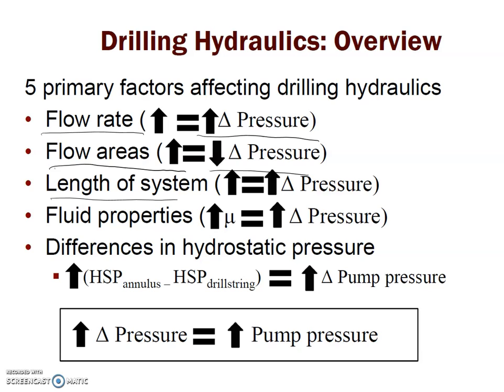requiring more pump pressure. So eventually, as the pressure drop increases, you would need higher pump pressure because you need to take the fluid from the surface, all the way back to the surface through the annulus, right? So the higher the pressure drop, you would need to insert more pressure to your fluid in order for your fluid to reach the surface.